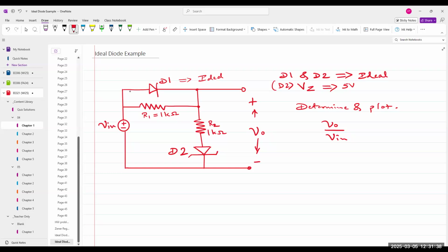It's the reverse bias that we have to take into account. So when it is reverse bias, what happens? Below 5 volts, it's off. Above 5 volts, it's on. And that's how you would approach it. If you keep these basics in mind, you'll be fine in the final exam, at least for one problem.